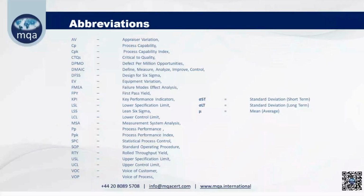Please, can you differentiate CP and CPK? See, CP is process capability. The formula is tolerance. What is tolerance? Plus minus 0.1 means total is 0.2. Now what is CP? Process capability is 0.2 tolerance divided by 6 sigma. Okay.